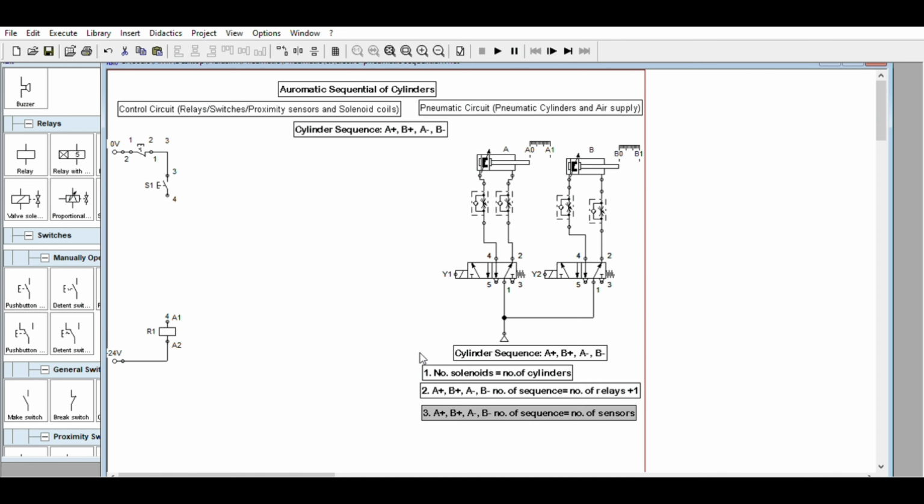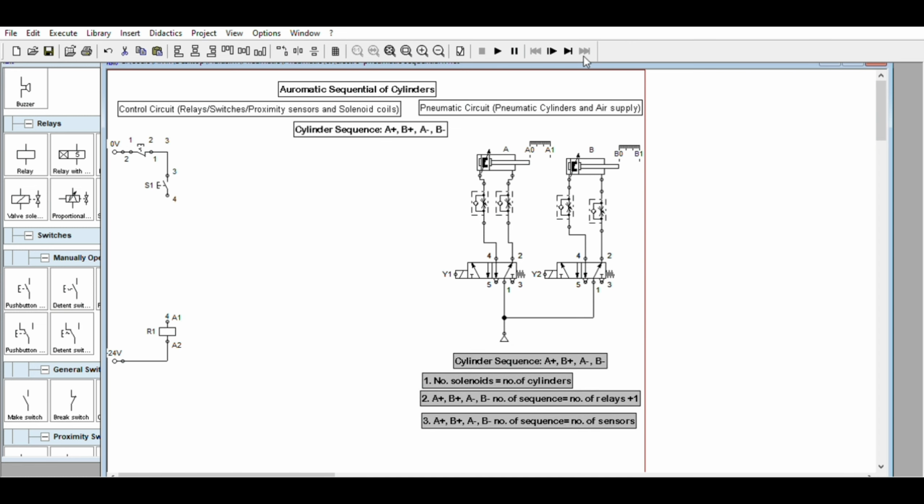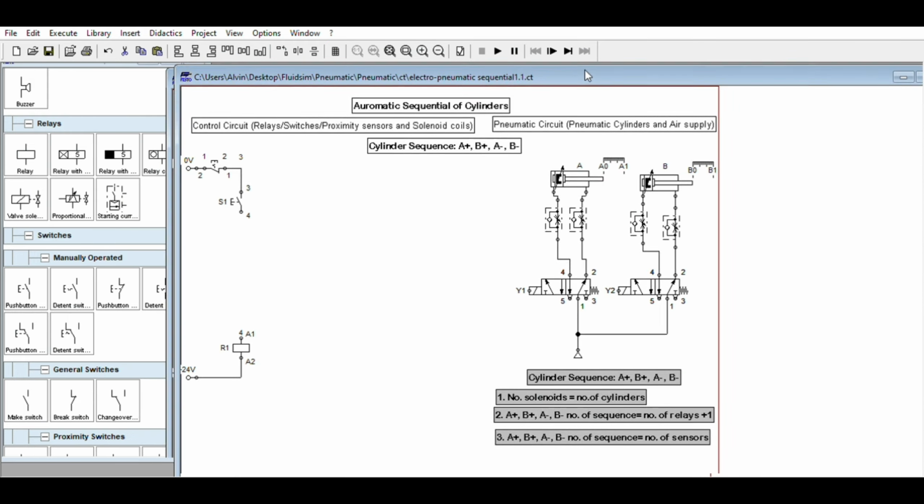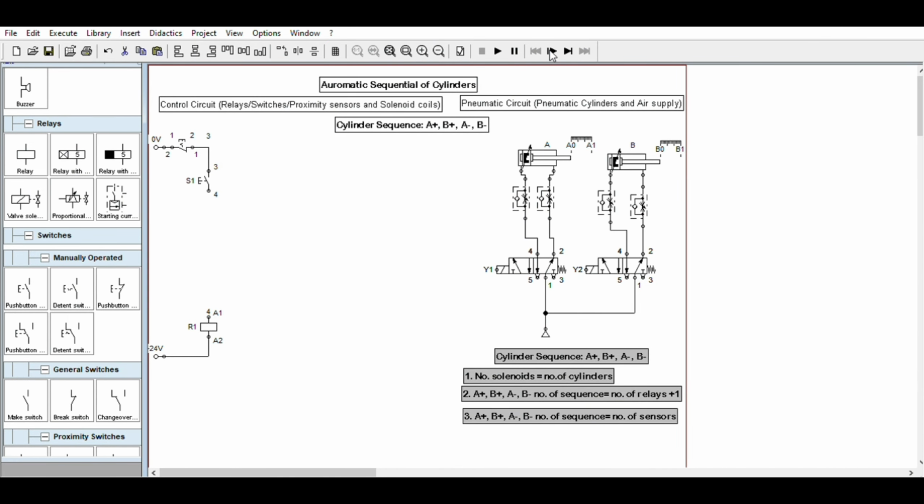These are the basic steps we need to make the electrical circuit. And of course, the basic knowledge of electrical controls using relays, contactors, push buttons, timers. They have similar operations here because we have electrical controls driving these motors. These are relay coils, and relay contacts are the equivalent.